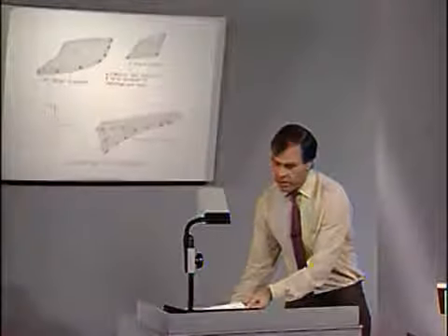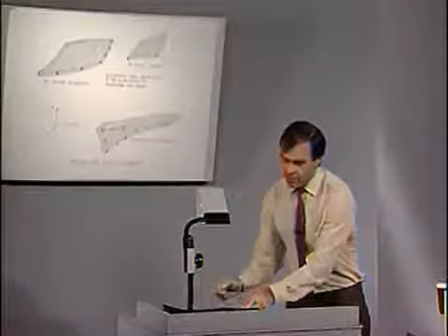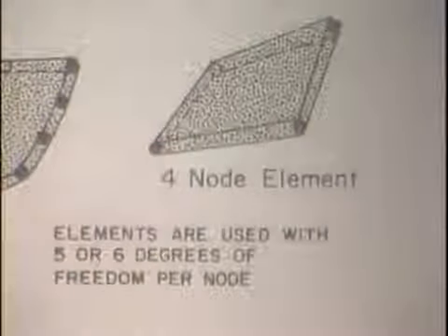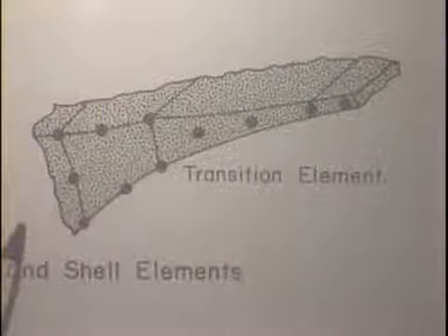And shell elements, we talked about the use of the 16-node element and the MITC4, the 4-node element. We also talked briefly about transition elements that are used to model shells or thin structures that couple into solids.